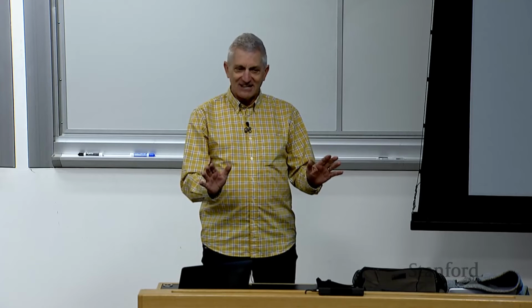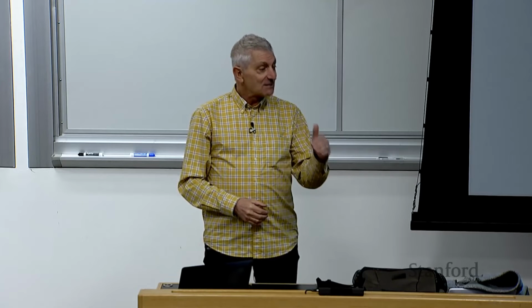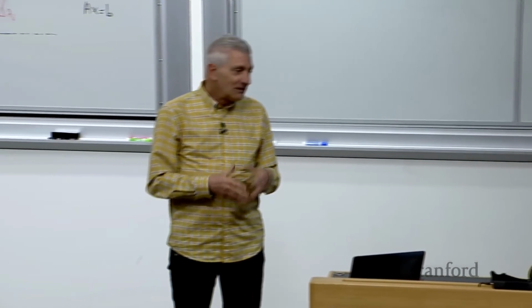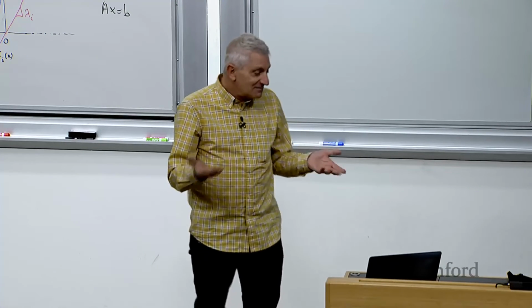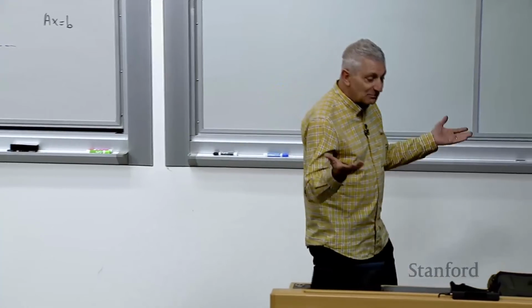Everybody following this? So now I crank up the supply voltage. And again, sorry, this is only for people who know about circuits. The supply voltage is like 2 volts. I set it up to 50 millivolts, and I attempt to solve again for an equilibrium point, right? So what does any chip look like when I put the supply voltage to 50 millivolts? It looks like a resistor, right?